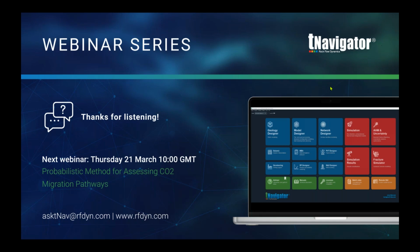Can you include seismic interpretation, such as seismic attributes, into your reservoir model? Yes, for seismic, we definitely can do this. We can bring in our SegY volumes, our ZGY volumes. We can calculate attributes here, or of course we can just import attributes from second-party software. We can then upscale this to our model or resample it into our grid, and then use this as either a trend or something like co-kriging, and then use this in our model as well.